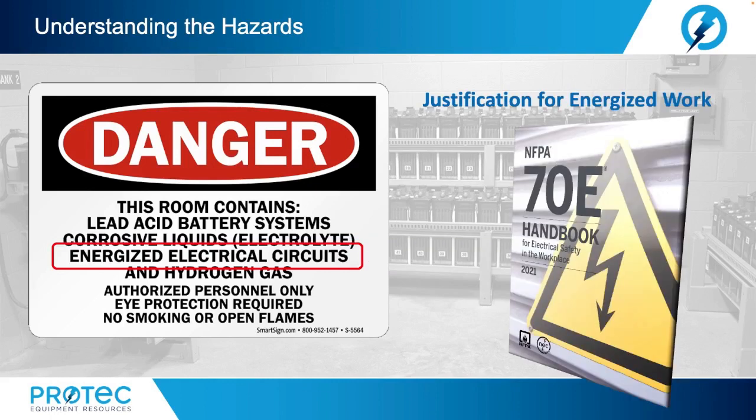Now, since we are working on an energized DC system, we need to ensure that the work that we are performing is justified work as defined in the NFPA 70E or the Canadian CSA Z462. The 70E or the Z462 basically states, energized work will be permitted where the employer can demonstrate that the task to be performed is infeasible in a de-energized state due to equipment design or operational limitations. Now, as we established earlier, by design, a battery cannot be turned off.